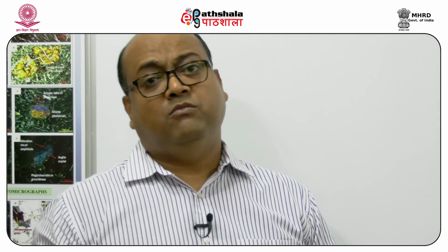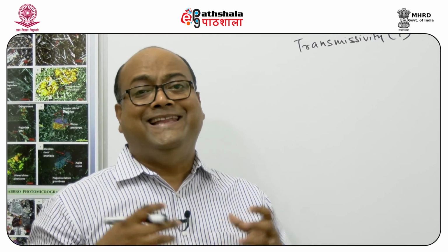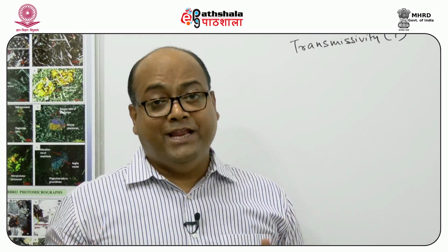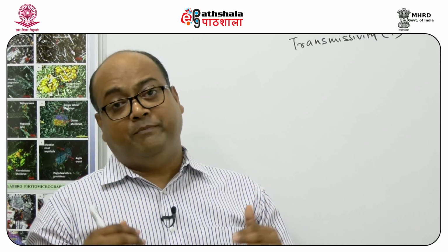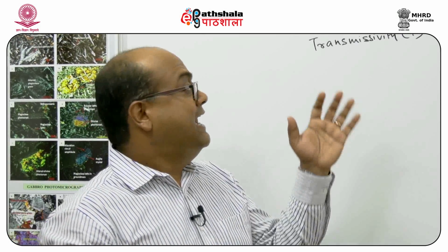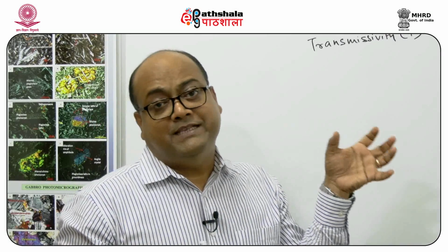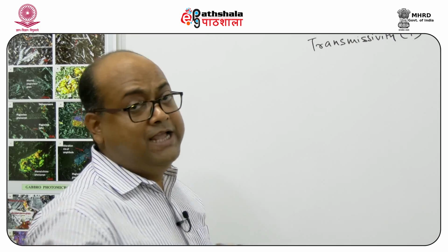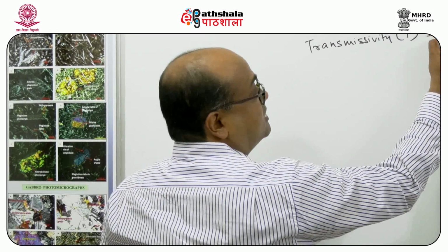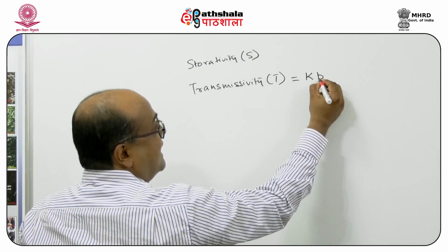It basically says how much water will be released from a unit area of aquifer if there is a unit drop in hydraulic head. And the transmissivity is a property of the aquifer which shows how the water is flowing from one side to the other. And if you remember Darcy's equation, this is given by K times B.